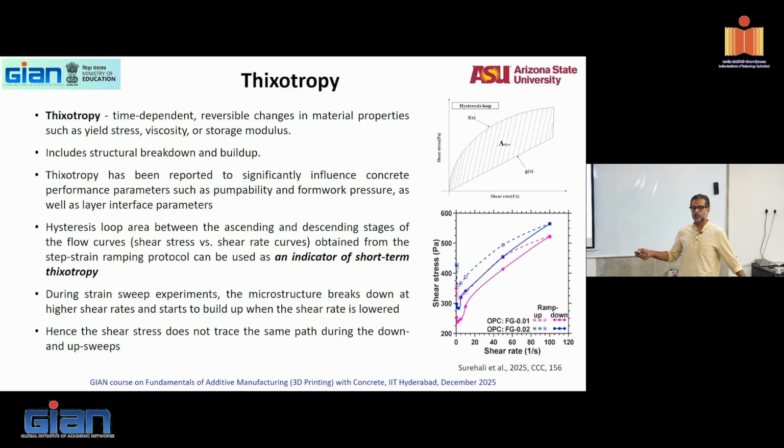This is a short-term thixotropy because I am doing whatever instantaneous. I mixed it, I'm doing my test instantaneously. That is thixotropy at time 0, very short. I can do the same test after half an hour of mixing, after an hour, after 2 hours of mixing, and the build-up and the breakdown will be different, right? The area under build-up and breakdown will differ depending on the thixotropic qualities of the material. If the material has a higher level of thixotropy, you are able to build it up much better. Is the idea clear? I'll show you some more examples as we go through.